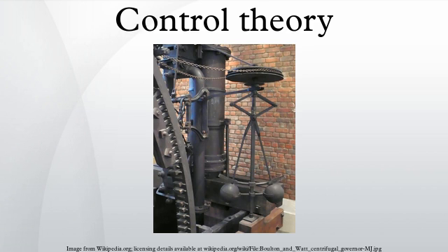Topics in control theory. Stability. The stability of a general dynamical system with no input can be described with Lyapunov stability criteria. A linear system that takes an input is called bounded input, bounded output, or BIBO, stable if its output will stay bounded for any bounded input. Stability for nonlinear systems that take an input is input-to-state stability, which combines Lyapunov stability and a notion similar to BIBO stability.